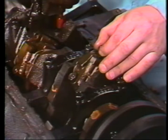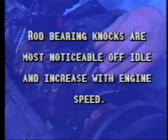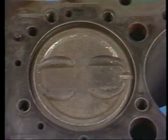Familiarity with the noise prints of the responses will help us quickly identify the correct response to this simple choice question. A worn rod bearing knock can be eliminated as the cause of our problem. Rod bearing knocks are most noticeable off idle and increase with engine speed. They become louder when the engine is unloaded and usually disappear when the spark is eliminated from the affected cylinder.